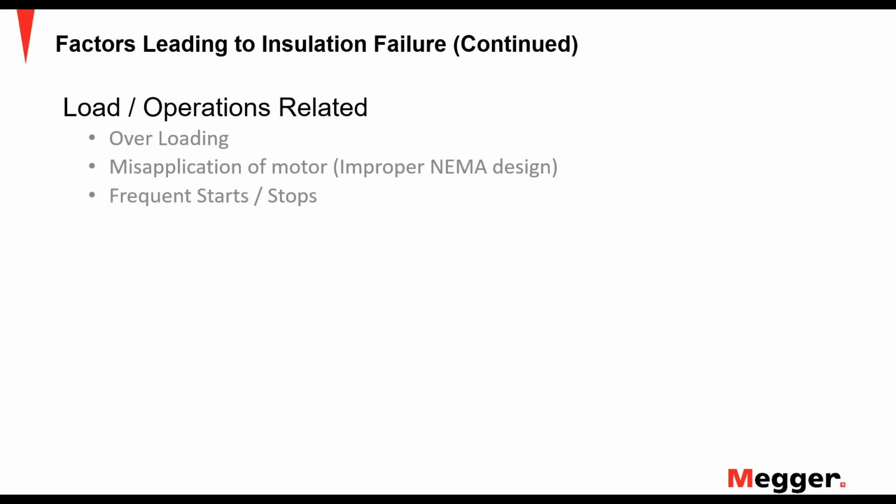Frequent starts and stops. Not only is the starting process, as Abel described to you, hard on a motor, it's probably the worst thing you do to your motor on purpose is to start it, but back-to-back startups are even harder, because as we start that motor, we get that rapid heating. The motor heats up because of that inrush current. And if we shut the motor down and start it again, right back to that, our motor's already hot, and it's going to get even hotter that second start.